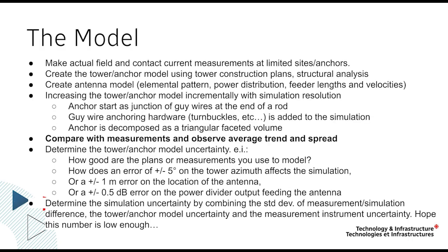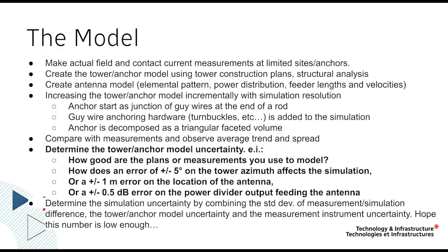Then we compare the measurement and observe the trends in the spread, because we need that in the future for determining the uncertainty. And then we have to do a sensitivity analysis to see how good is our simulation of the tower and the anchors compared to reality, because we used design blueprints of towers. We don't actually go and measure the real height of the things. People do that for us, but sometimes they make mistakes.